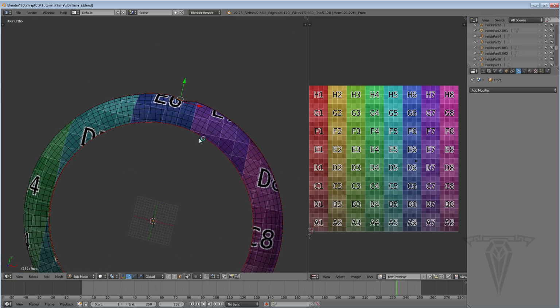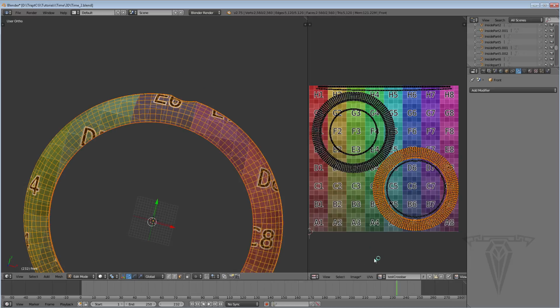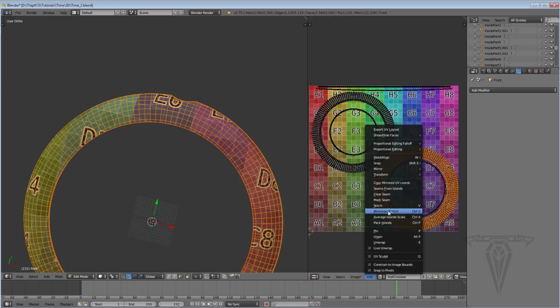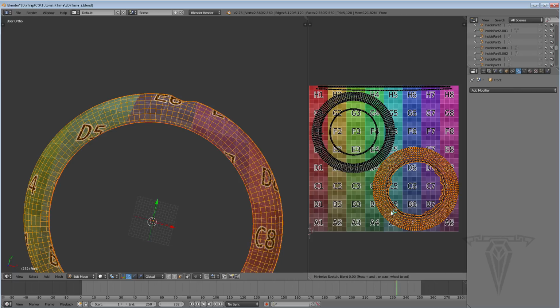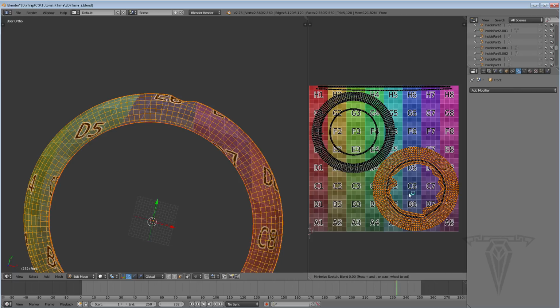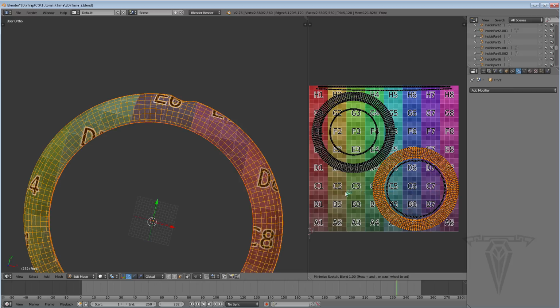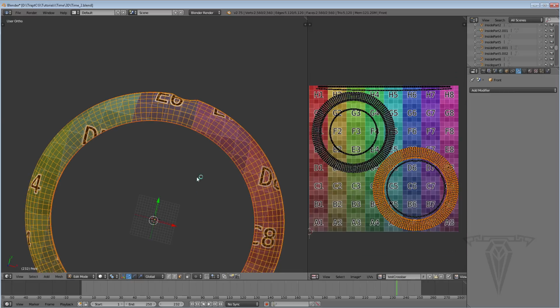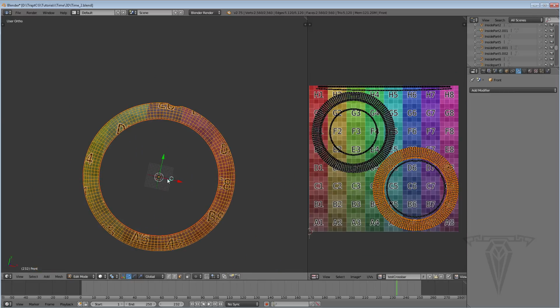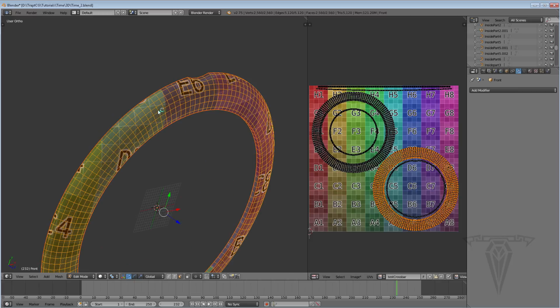Let's go ahead and select all again. I'm going to select this group, and I'm going to just try seeing what happens when I do minimize stretch. Oh, and it makes a mess of the geometry. So that's 0%. That's 100. 1%. Yeah, let's go 1%, gives me a much cleaner outlook. So I'm good with that. Okay. So everything's looking good, cleaned up. I'm not getting any weird distortions.